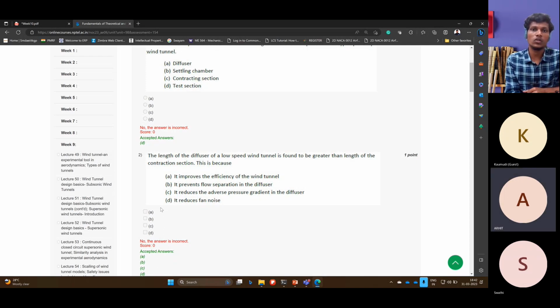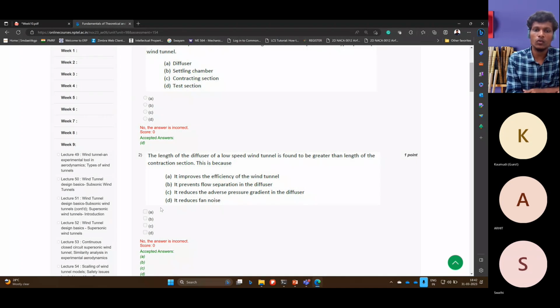For low noise, this is a very vast area: how to reduce the acoustic noise generated inside any flow exiting from either subsonic or supersonic nozzles. If you are creating an exit flow, you can nullify the effects with a long divergent section. You can better understand that when you have the practical experience of seeing a flow through convergent divergent sections.